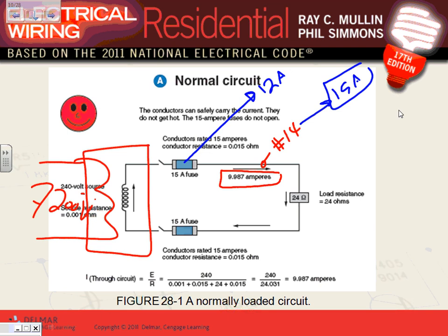So here's how they came up with the current, guys, from Ohm's law that you did with Gary and Chad, and with all our electrical instructors. You take the voltage divided by the impedance of the load, which is substantially more than the impedance of the conductor. So if you look at the 24, here's my 24, substantially more. Then you add to it the impedance of the conductor.